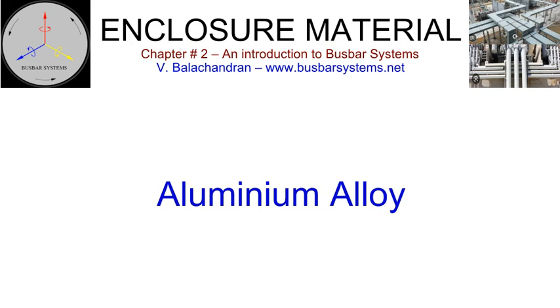Grades 1050 and 1350 have excellent conductivity, while grade 6101 exhibits good mechanical properties at a marginal compromise with conductivity. Grade 5052 displays good properties for corrosion resistance, workability, formability, and weldability. Grade 6061 is extruded and displays good mechanical properties. These alloys can be heat treated and are available in different tempers. Depending upon the nature of specific requirements, with respect to conductivity, mechanical properties, and resistance to corrosion, enclosure material is chosen from a wide range of treated alloys.